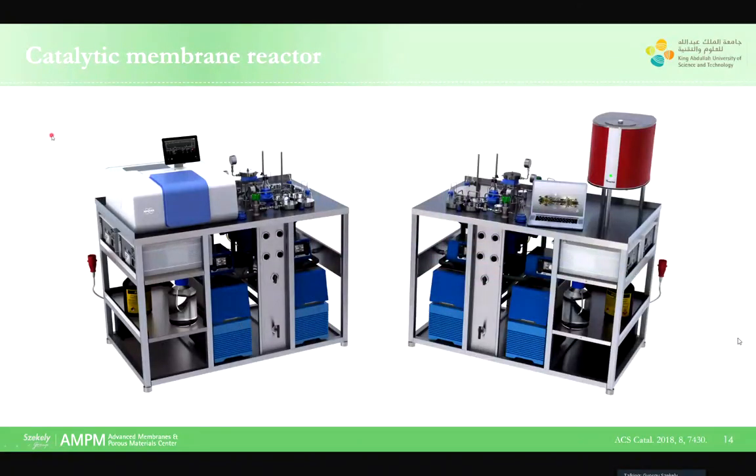Okay, so here you can see the actual catalytic membrane reactor that we have in the lab. So we actually have two of these membrane reactors. One is coupled with an inline FTIR, and the other one is coupled with an inline NMR. So with process analytical technology, we can actually continuously follow the reactions that we perform in these reactors.